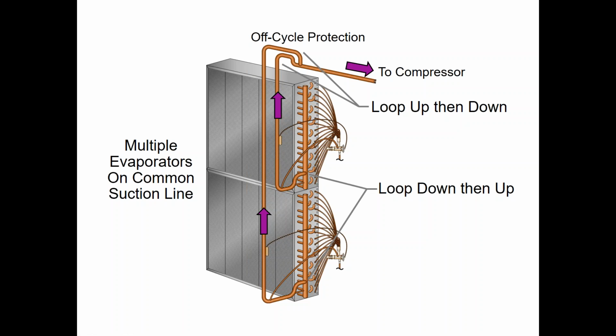Okay, so going back to comfort cooling, full face application, but we can get into multiple circuits. Here we're just showing a single circuit on the top, single circuit on the bottom. In reality, we typically will have a row split coil. So we'll have one circuit on the entering side, and one circuit on the leaving side of each coil, which, if we had that here, we'd have two TXVs feeding the upper coil, two TXVs on the lower coil, and of course, 4 suction pipes.